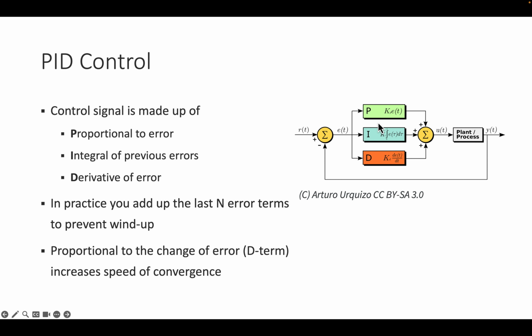Of course, tuning these three values is a lot more complicated than it has been with P control, but what you can do is start with a P controller, then introduce the additional terms and slowly reduce the P value, and see how you can tune the behavior to be better than a basic P controller.